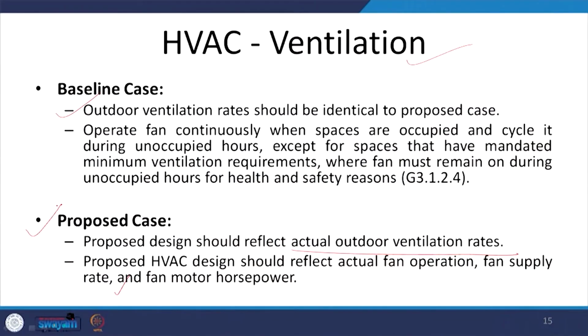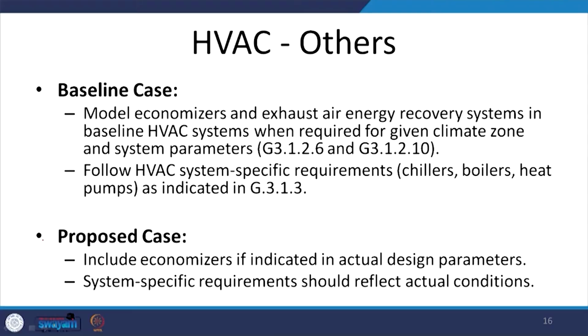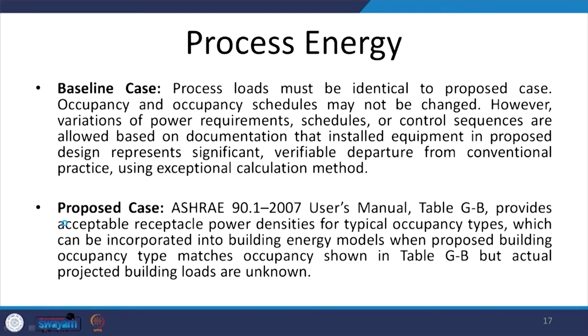So, the schedules of operations which are programmed, which are specialized, may be used in the proposed case, but not in the baseline case. Additionally, the baseline case will not model the economizers and exhaust air energy recovery systems, while they will be included in the proposed case to give an advantage of design to the designers.